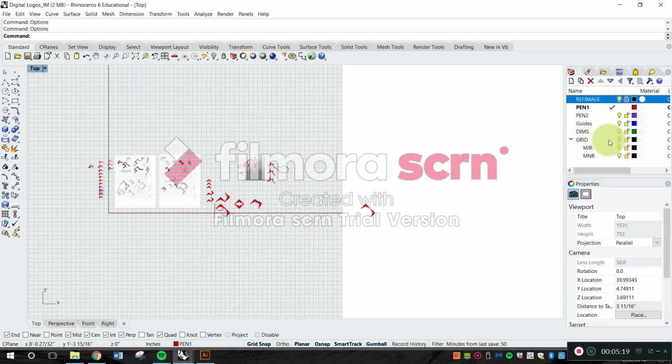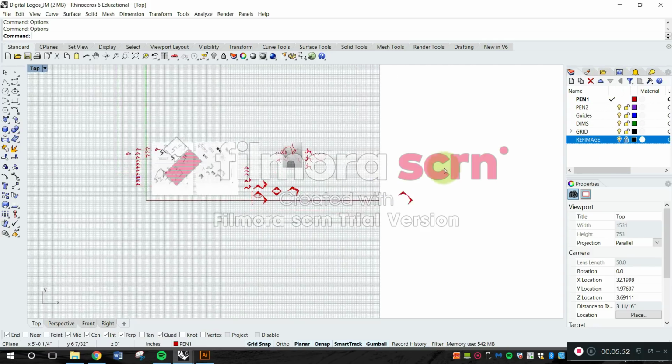Layer use, as you have been able to see, is critical when you're working on your drawings. In this case, we had the reference image that we had locked in order for it not to move. Additionally, you are going to sometimes want to move these layers. So if you select one of these layers, there are these arrows right here on the top, and you can work on the order of this. So I'm going to send my reference image all the way to the bottom, since it's the one that I'm using the least.